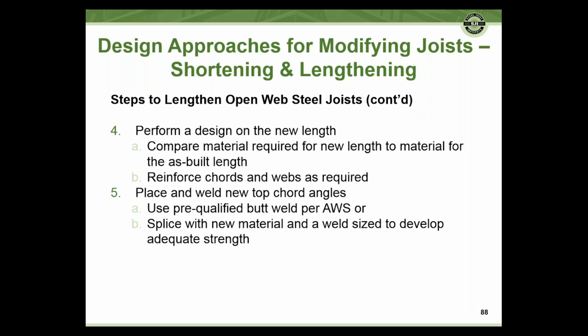So you're going to have to use a pre-qualified butt splice for welding that new top chord angles in. Make sure you splice that new material and you develop adequate strength. Always recommend, if you're going to splice it in, add a little reinforcement at that splice. It's just a good safety measure to do. It helps protect that splice just in case, and it's cheap insurance.